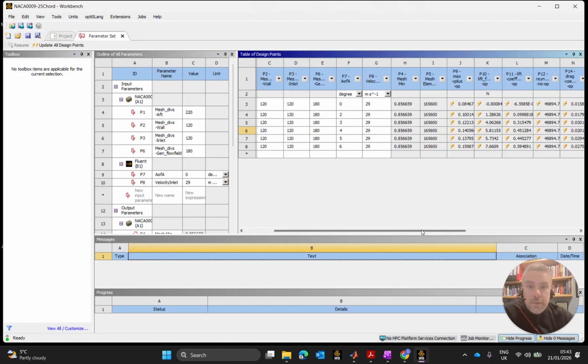Or maybe there's been a laminar separation bubble developing at an angle of attack of 4, and when I put it at 5, it hasn't reattached. So there was laminar separation earlier that hasn't reattached. So can you really call it a bubble? Maybe not. But it has broken off the wing when I put it up at 5 or 6 degrees, and when it hasn't reattached, it hasn't just caused a bump, it's caused potentially a region there of minimal stall.